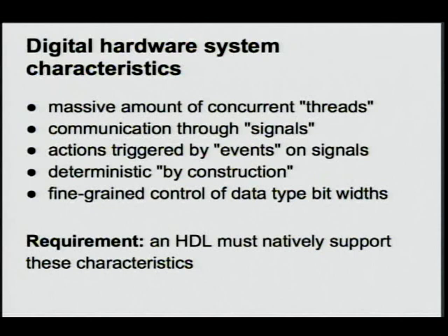And then a final characteristic is that we want fine-grained control of bit width. We don't want to use 8 bits or 16 or 32 for every variable. That would be a waste of resources. So we want to control the bit width in a fine-grained way. So here we have a set of requirements that an HDL must support.